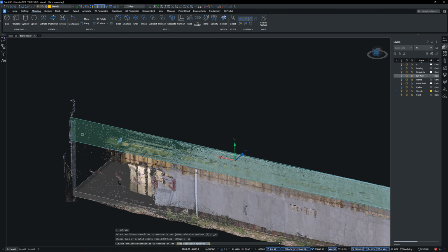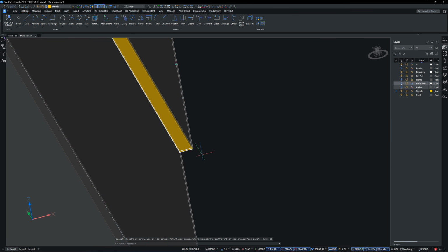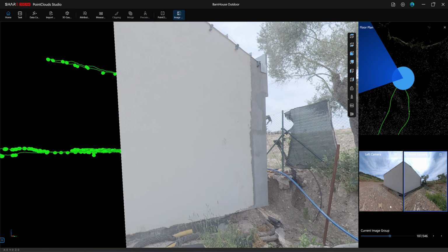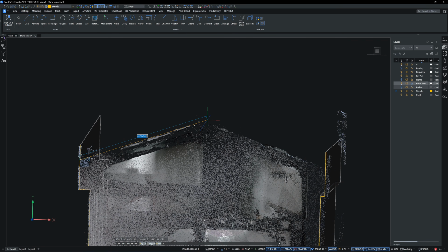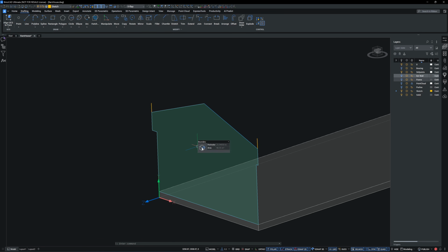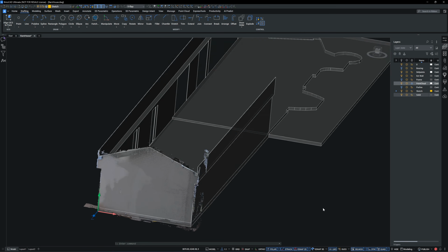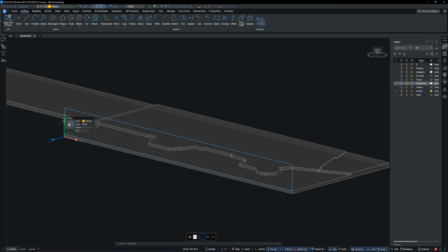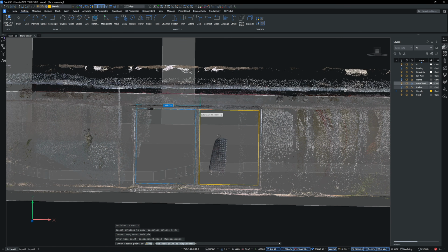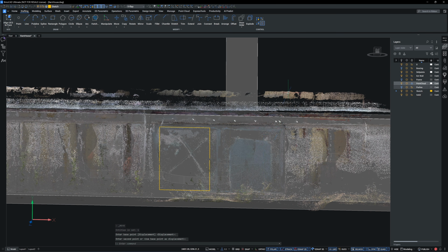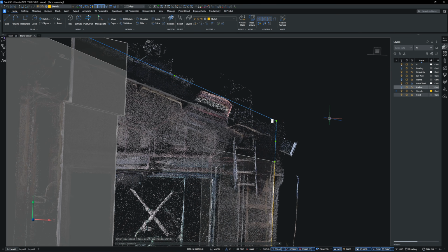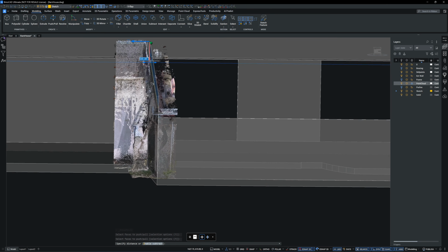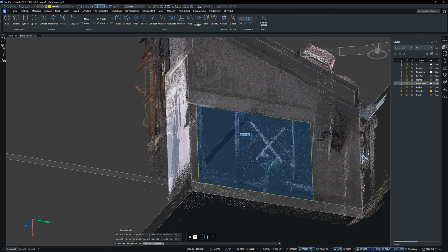I noticed some glass wool in the scan data. It's likely placed between the outer and inner drywall layers, and here the wall thickness is around 20 centimeters. Glass wool provides thermal insulation only. If sound insulation is also required, rock wool should be used instead. Metal sheeting roofs usually generate a loud noise during rainfall. To reduce sound transmission, materials like rock wool or heavy gypsum board can be used.